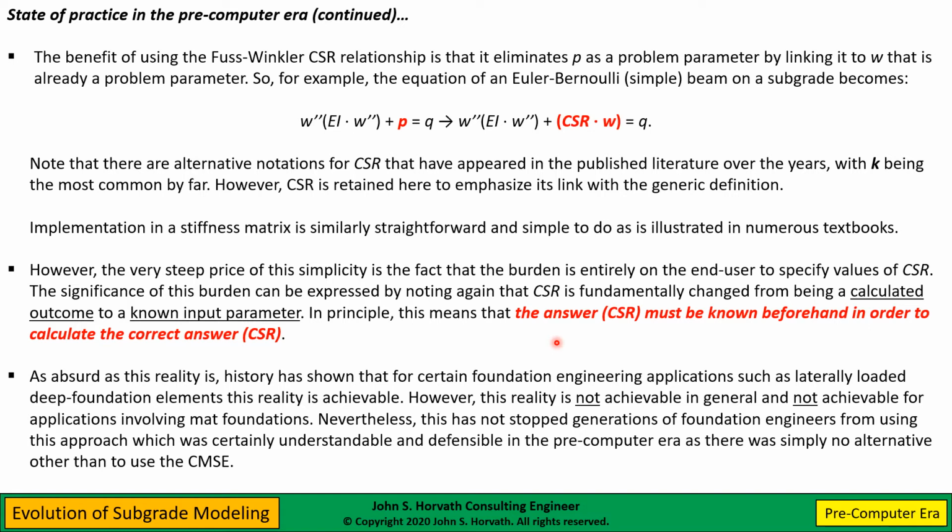With laterally loaded deep foundations, we've been running instrumented load tests since the 1950s, 1960s. So we've created this massive database of answers that people have correlated with soil types, so that, yeah, we can forecast these PY curves, which are basically, we're forecasting the answer beforehand.